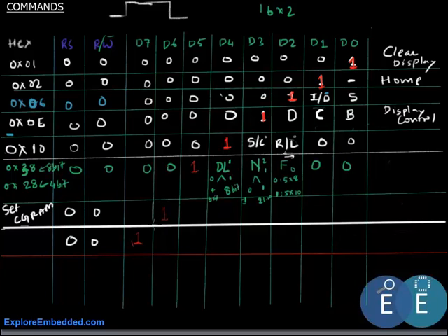So this is basically used to display custom characters on the LCD. And the next command sets the address for DDRAM, and this we would be using. What this does is, this bit is 1 and we have 7 bits left, so the address range would be 0 to all ones, which is 127 in decimal.